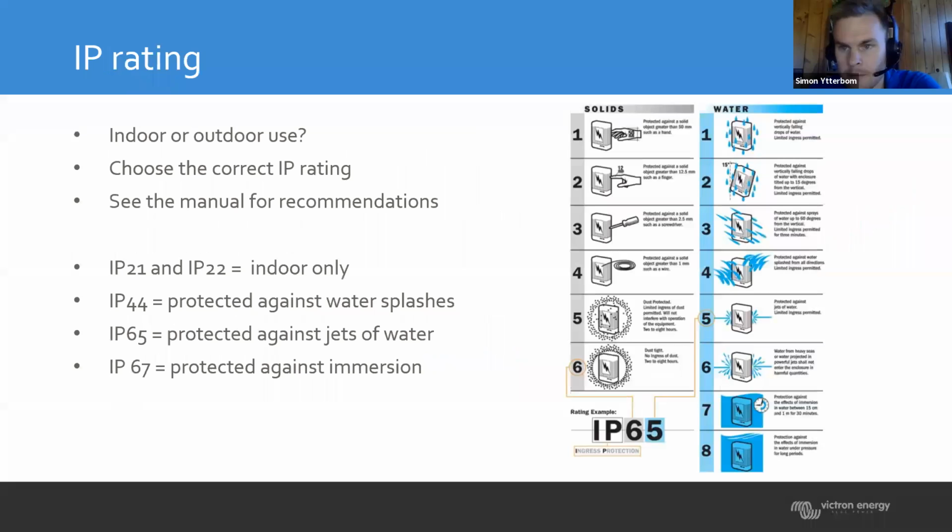Another thing to take a look at is the IP rating of your components. If it's going to be used where there's water, splashes, small boats, you might want to have a higher IP rating. So make sure that your IP rating is up to the task according to where you're going to place the unit. If you're using something in the engine room, then a water rating might not be needed. But if you're using the unit outside or outdoors or wherever, it can be very important for the life of the charger or inverter, and so on.